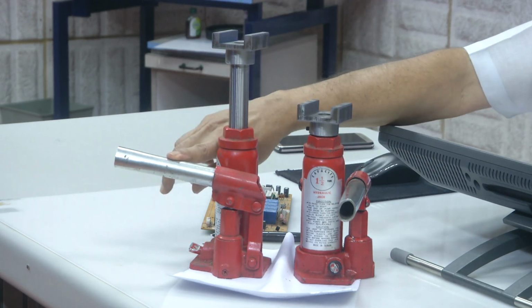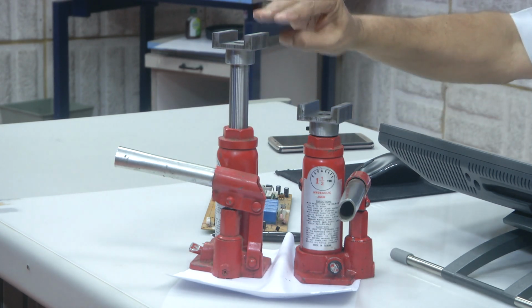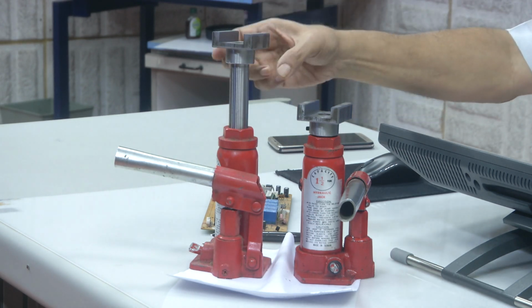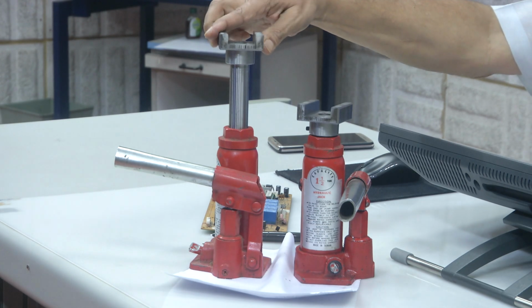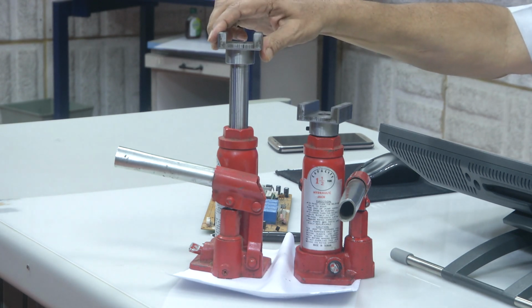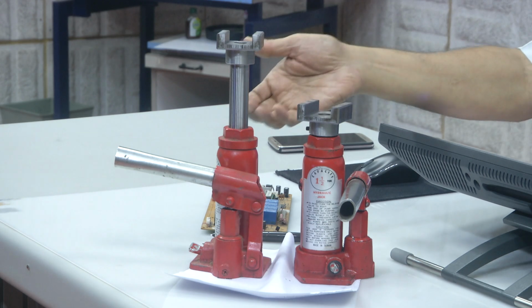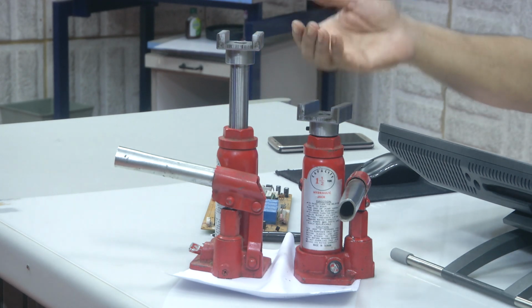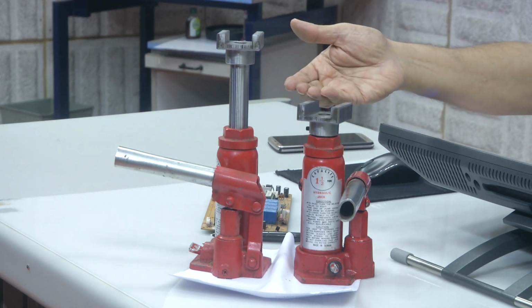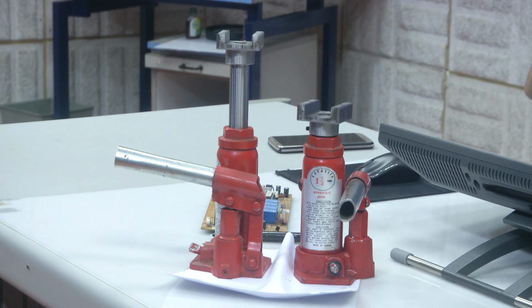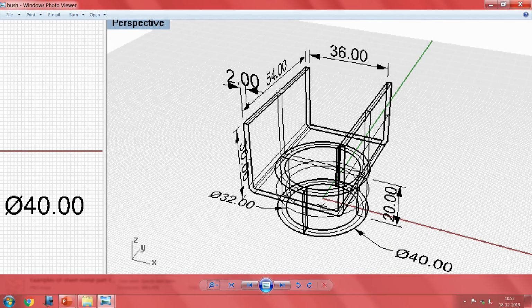Once you operate this hydraulic jack, it has to be raised this much to make sure that this top member engages with the chassis member, and then afterwards lifts the wheels clear of the floor, and afterwards some other safety backup support is there. Now that you have seen the whole, if you see the drawing, it is not enough if I just mention some dimensions here.